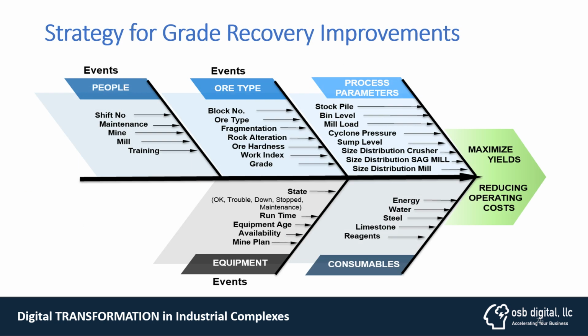In the industrial practice, what we do is that we take the events of the type of ore and we do the grinding, we define the particle size distributions, and then we identify the state of every piece of equipment so we can assess when to use the model, when to do the prediction, and when not to do it, because if it's not working correctly within the windows of operation that are consistent, it's impossible to predict anything. Same would happen with an instrument or anything like that. And we calculate also the consumables. That was presented in another paper which defined the hidden losses.